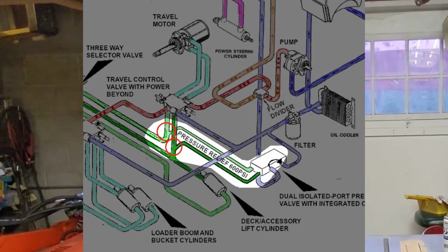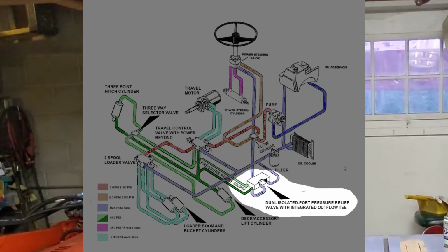However, I would have to have two different relief valves, one for each work port. The raise-up line's relief valve wouldn't do anything to help the lower down line, so each line is going to need its own separate valve, and they cost about $100 each, and it's going to be a rat's nest of hydraulic lines to hook them both up. So, does anybody sell a dual port relief valve?